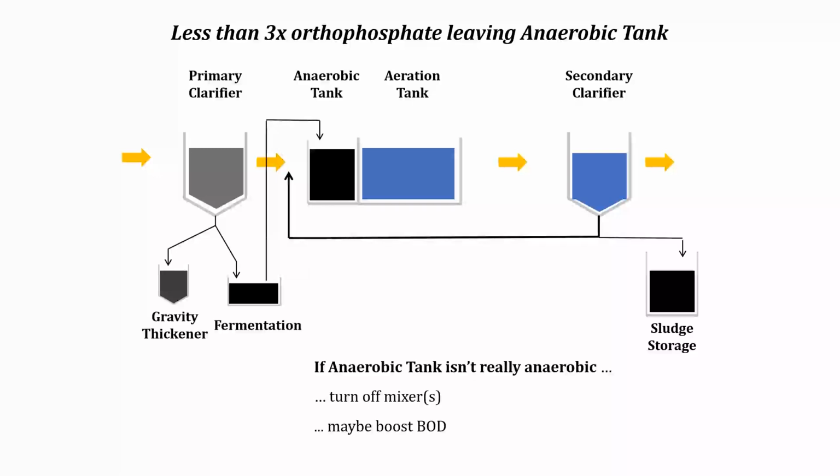So you want to sample your effluent for your compliance under normal operating conditions, which would mean not during a storm flow. And that's more representative of your effluent. That's also going to give you better numbers for phosphorus.